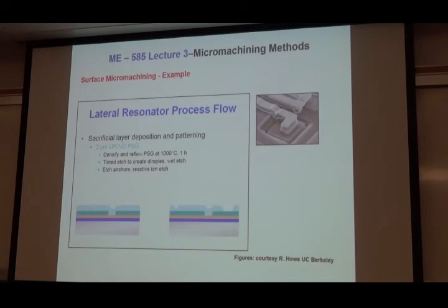Okay, any questions so far? So we're building the structure layer by layer. So what do you think is going to follow now? A question? Yeah. So between the etching to create those dimples, on the right side, and then creating the anchor, those are 2 different etching processes. Yes. So one's like a timed etch over reactive.